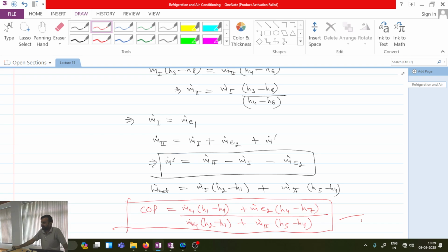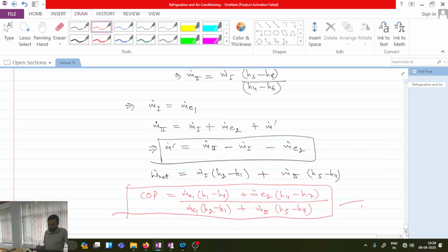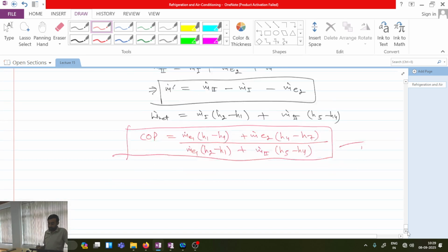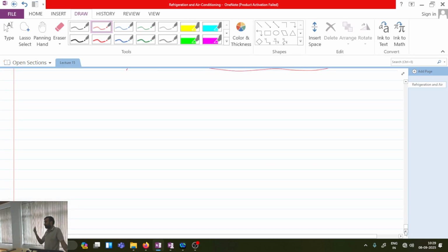Today, we will try to see another category of multi-stage systems, which are called cascade systems. Before going to cascade systems, first we will list down some of the limitations of the multi-stage systems and the need for cascade systems. It has been well established practically that if we operate within minus 30 degrees Celsius to condenser temperature, which is usually the ambient temperature, then we can operate with a single stage compressor.